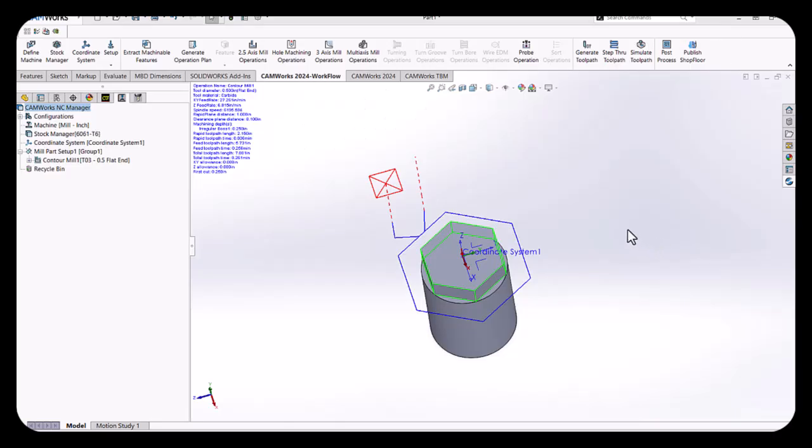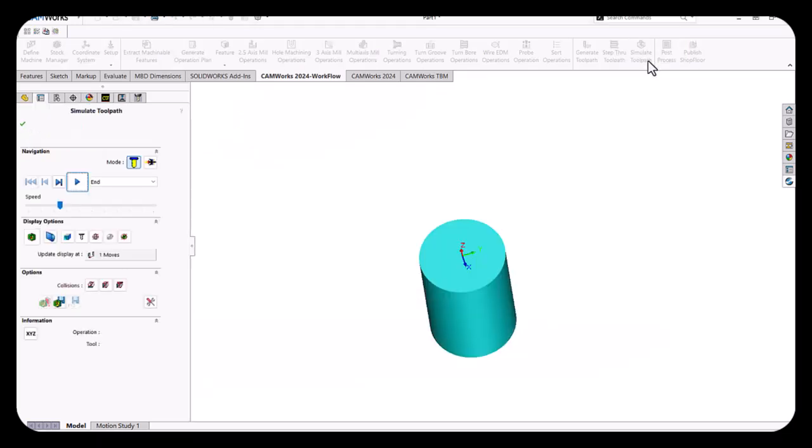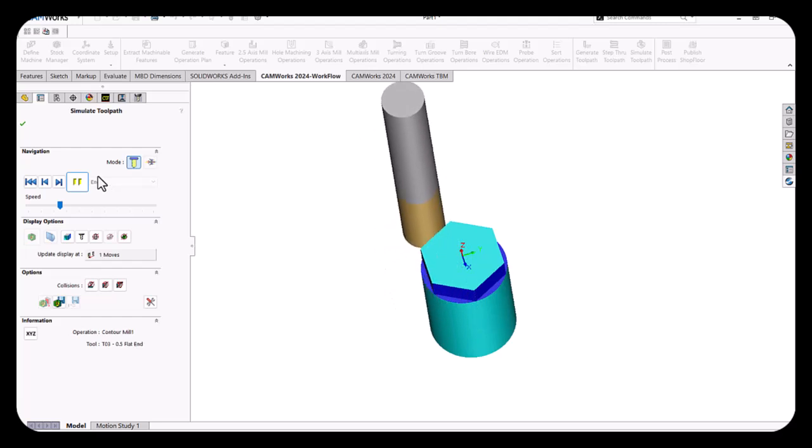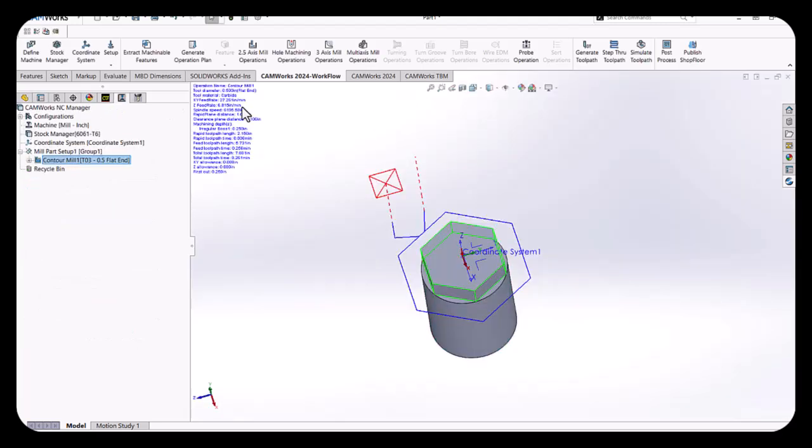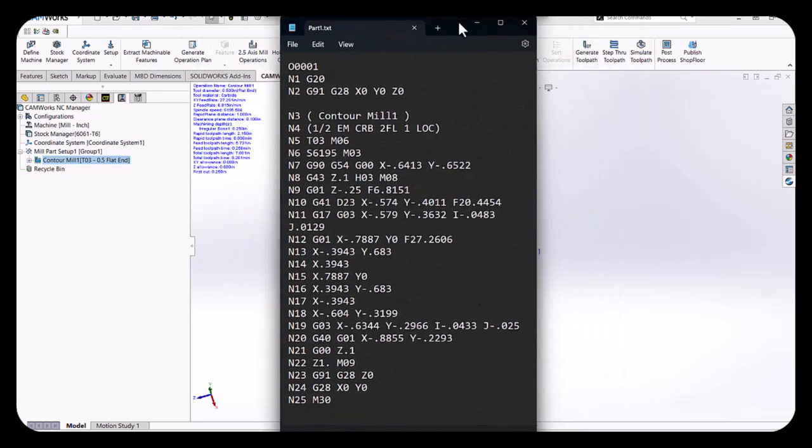We're going to start with a 1-inch piece of material and do a simple hex on it. I'm going to use a simple 3-axis mill post to go around this piece. It's going to look something like this, to create the hex 1/4 inch deep. So when we post it out, this is what it's going to look like.